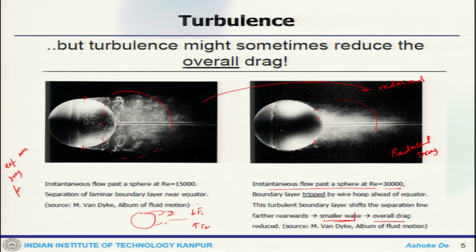But if you leave those factors aside for the time being, and just think about one side smooth and one side rough, with the ball approaching the batsman, that is where the swing happens because of this asymmetry in the radial forces. Primarily the reason behind that is the fluid mechanics. In one case it is a laminar separation, in the other case it is a turbulent separation. In this case the drag is reduced, or the adverse pressure gradient zone is low; in this case it is high.